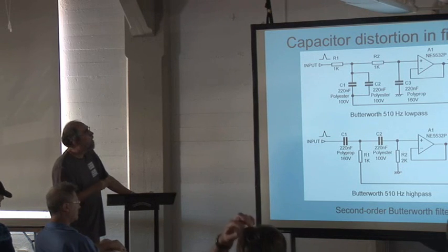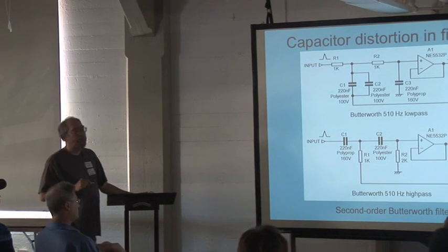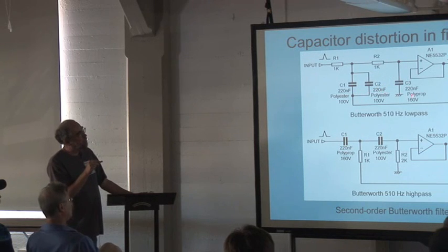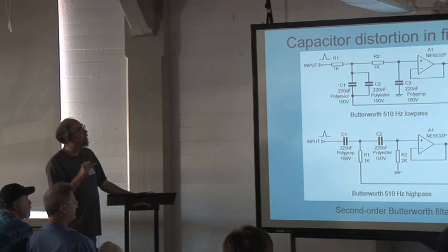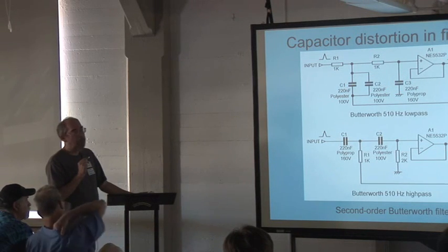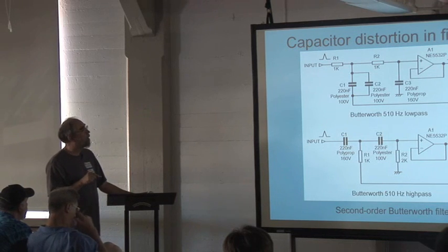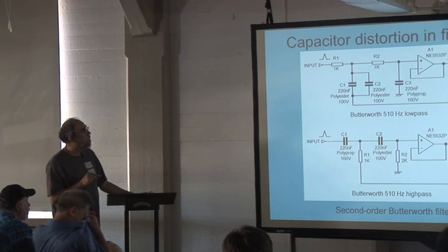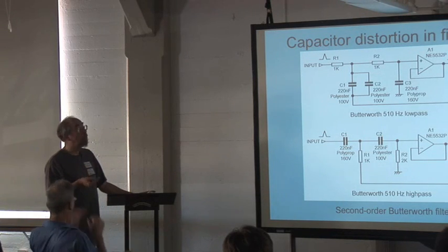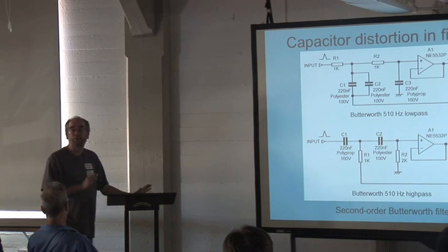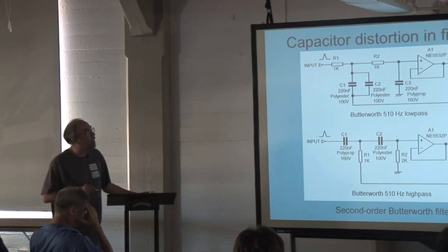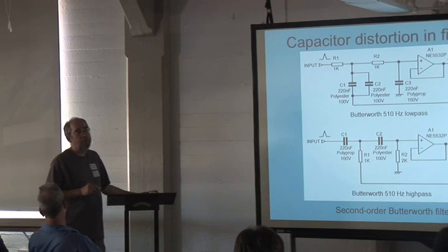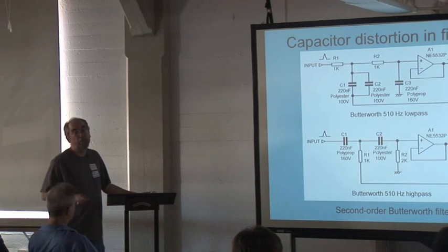Next. Now the interesting thing about this, and this remains a bit of a mystery, but once again, work in progress, is that you don't have to make all the capacitors polypropylene. If you make that filter there, and you put the polypropylene one there, and you put a couple of cheap polyesters here, that too is distortion-free. The distortion is centered on this capacitor here and not these two. Now, once again, my intuition fails on that one. I don't know why that is. I'm going to find out. But you could save quite a bit of money in an active crossover, because probably the polypropylene caps will be the most expensive part of it. They will cost you more than the op-amps, more than all the other components. If you've got something like a 470 nanofarad polypropylene, that's an expensive part. That's going to cost you, perhaps, I don't know what the cost would be here, $1 maybe, something like that.